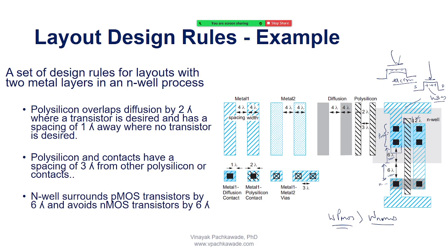Therefore, to have an equal number of charge carriers, or the same amount of current, usually PMOS dimensions are made bigger than the NMOS. That's what we call adjusting the length to width ratio. We are going to see that ahead when we move ahead.